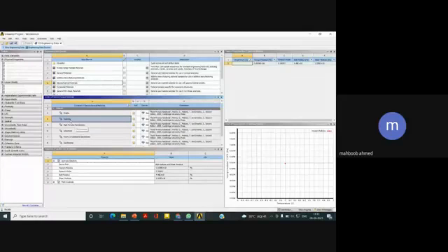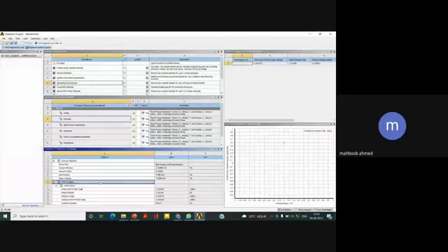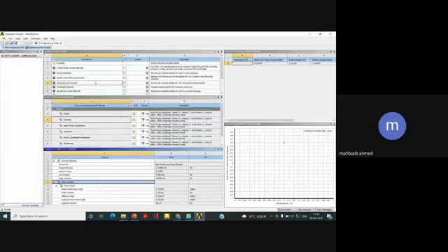For example, I want to know the properties of dolomite. So you can see these properties of dolomite given here. For example, its Young's modulus is given as 5.859e10, that is 58 gigapascal, 58 GPa. Poisson's ratio is given, and bulk modulus, shear modulus, and other parameters are also given, whatever the requirement is.